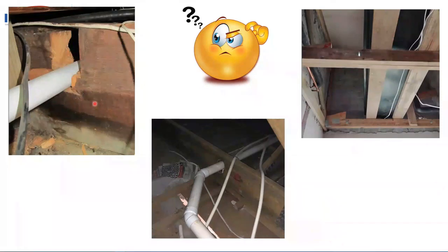You see they've cut that whole bottom chord right up to the batten that carries the ceiling boards. So that roof truss has come and gone. You can see the weakening on the middle one, and then you can see here that whole triangulation portion of what was supposed to be the support in this truss has been cut away to accommodate this installation. So you can see there's quite a bit of negativity around these specific installations when it comes to roofing, because we have got guys that sign off on roofing as professionals.